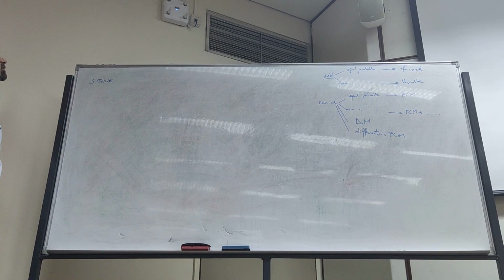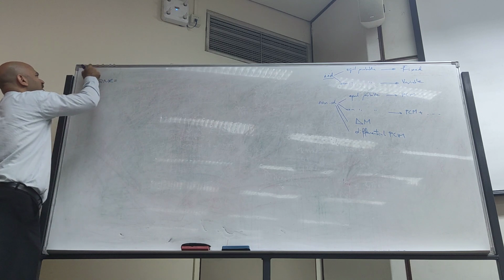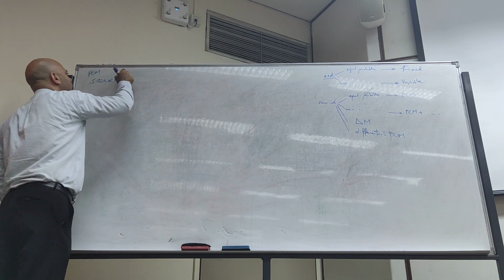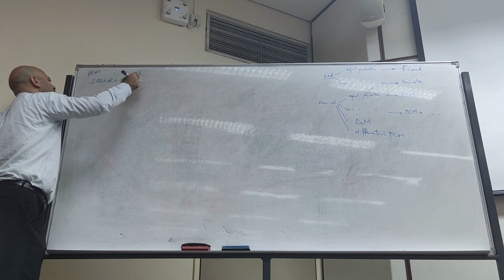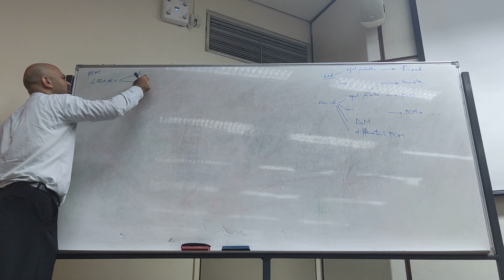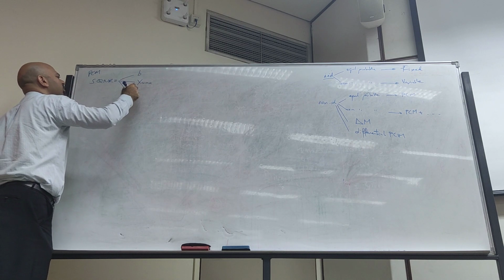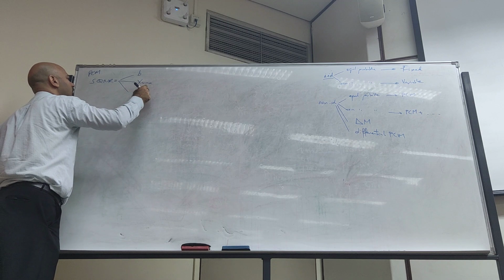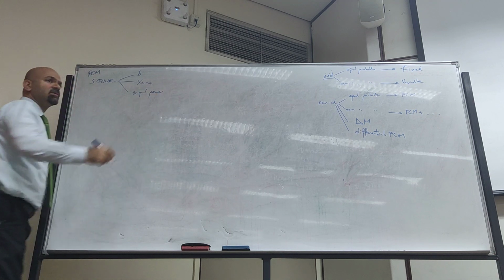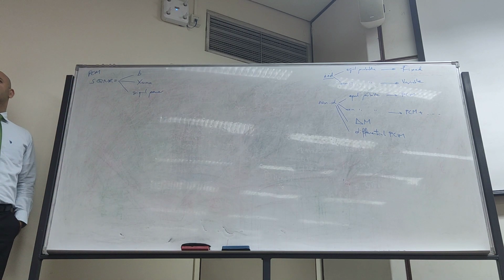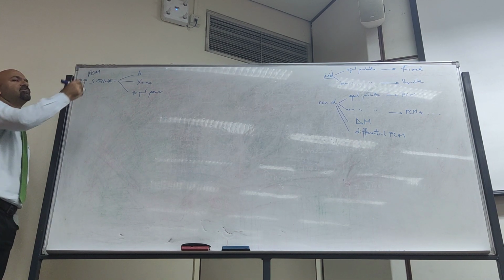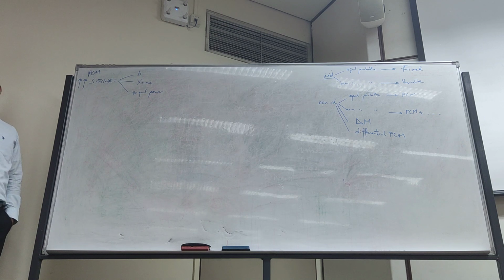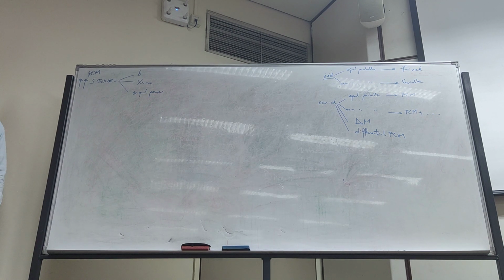So here, SQNR. Last time we obtained an equation for the PCM SQNR, and we saw that it depends on B, the number of required bits. It depends on the range, X max, I think it was named, right? And it depends on the signal power. And we said that always, obviously, it is a signal to noise, so we want it to be the largest possible. Good? So how to make it larger? We have these three parameters to make it larger. This is where we stopped last time.